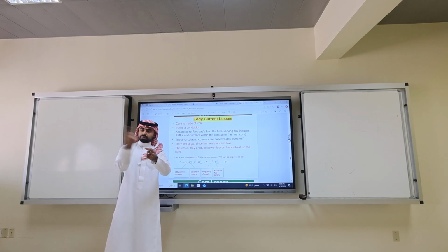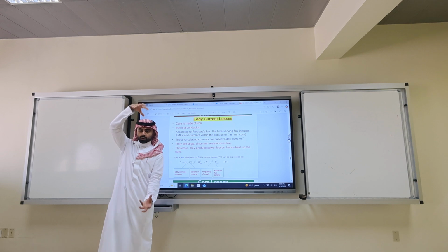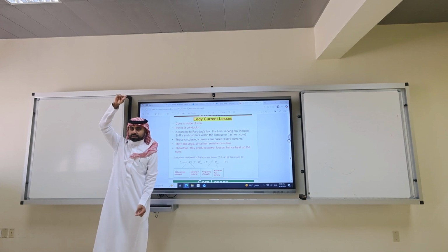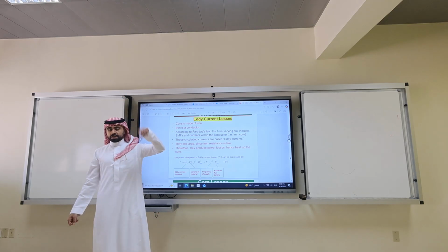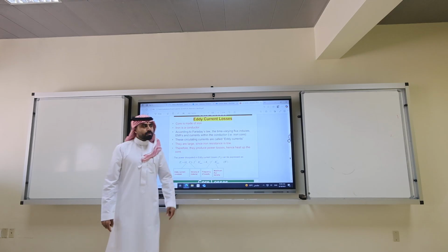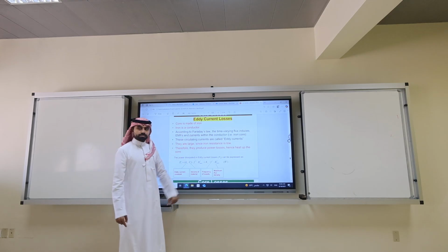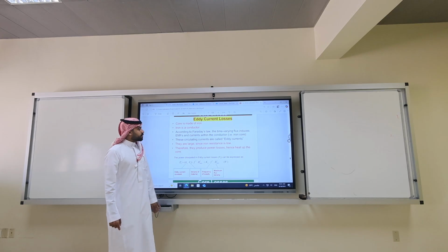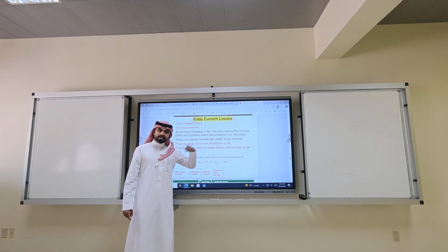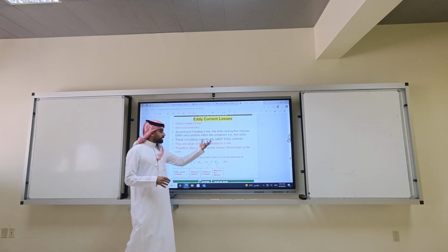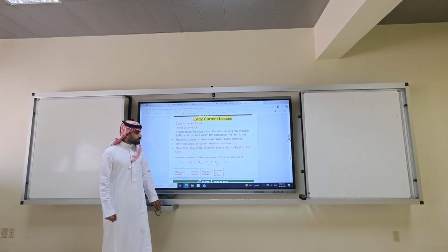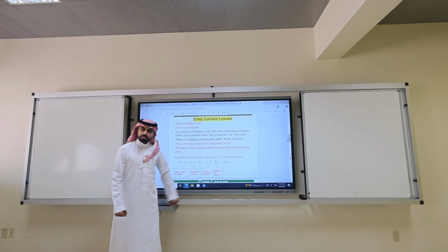Think about a looped coil. You pass the current and you put a steel. There are Webers going, but those Webers are fixed. The moment you change your current, those Webers are going to change. When they change, they induce voltage and current, okay? These currents that are rotating inside the steel, they're called eddy current, and they produce power losses, come up as heat.